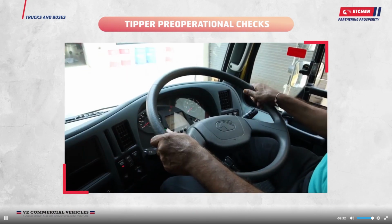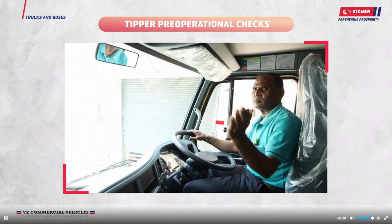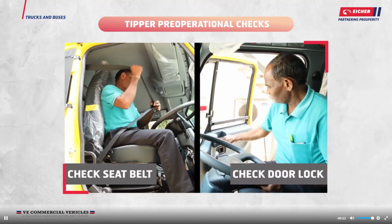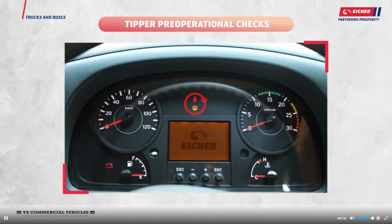Check horn for proper function. Check and adjust the rear view mirrors according to your seating position. Also adjust the blind spot mirror position. Check seat belt and cabin doors locking function should be locked properly. If not locked, warning lamp will illuminate in instrument cluster.